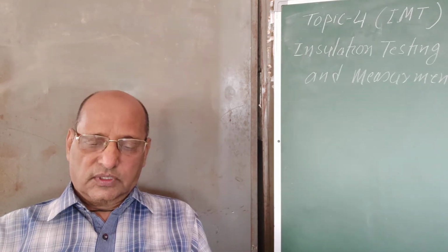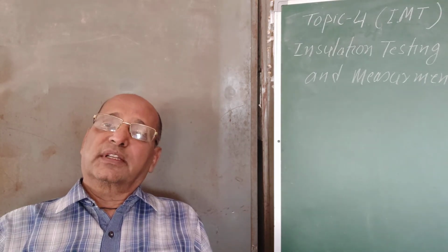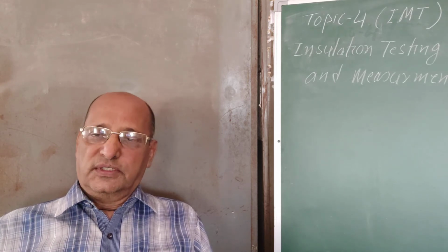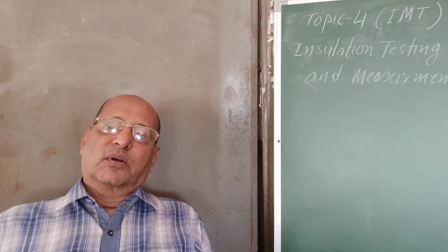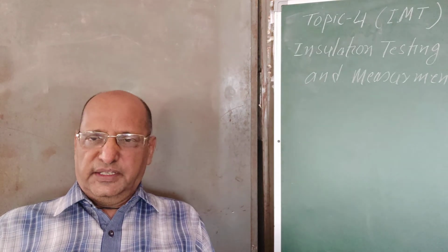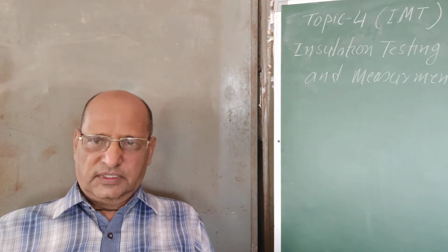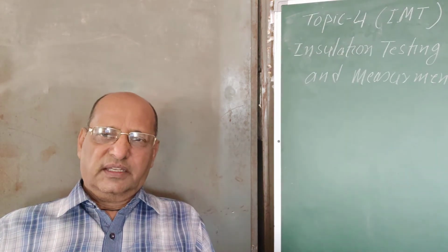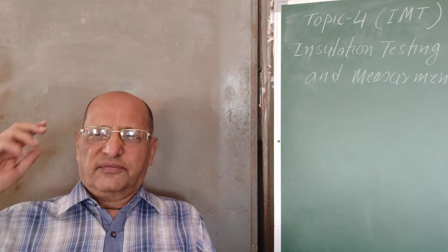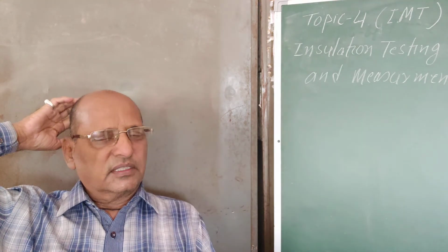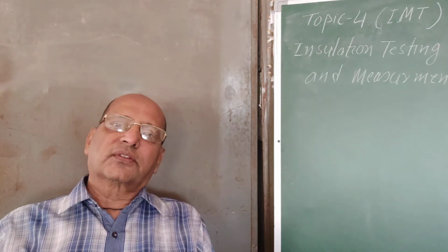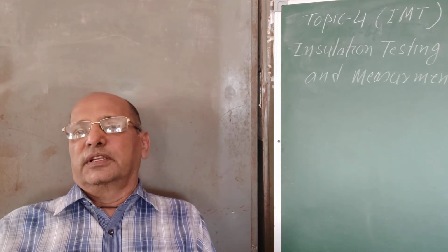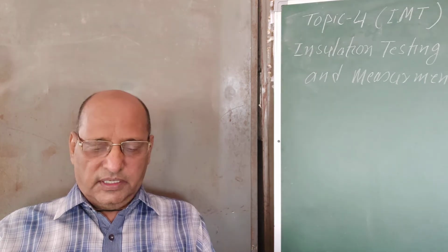For improving the resistance of this type of insulator, we have to check these insulators with the help of proper equipment, clean them, and look for hair cracks and porosity. If there are none, then you can go for a flashover test of the insulator, and by the flashover test we can easily find out the quality of the insulator provided.